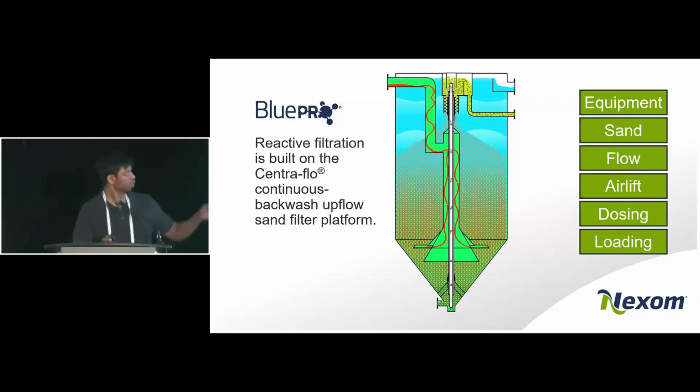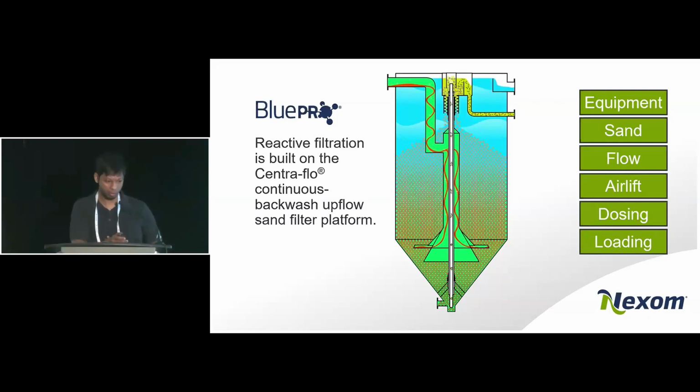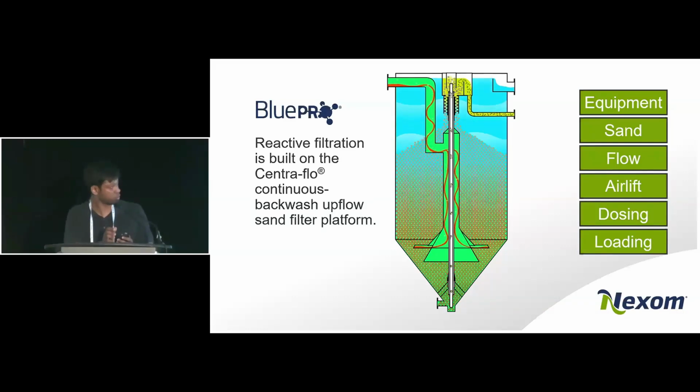So you can see here, the green water, which is the dirty water, goes down. The coated sand picks up contaminants, which is black, and it goes up into the wash box. In the wash box, the coated sand is cleaned up. Due to the impact, the coated sand separates from the contaminants, and the sand flows down through what we call the tortuous path, which is the black component at the top.